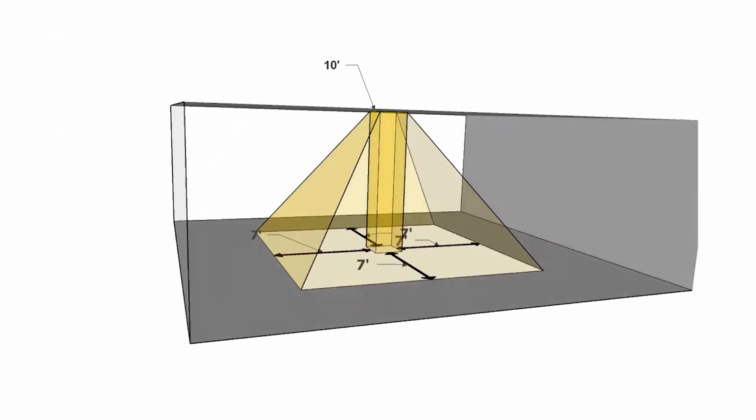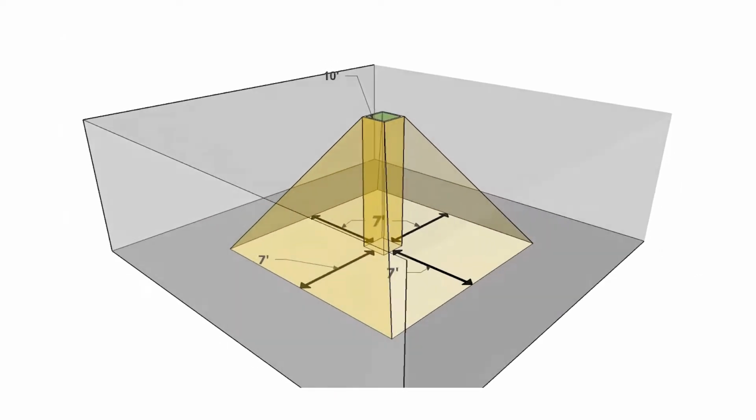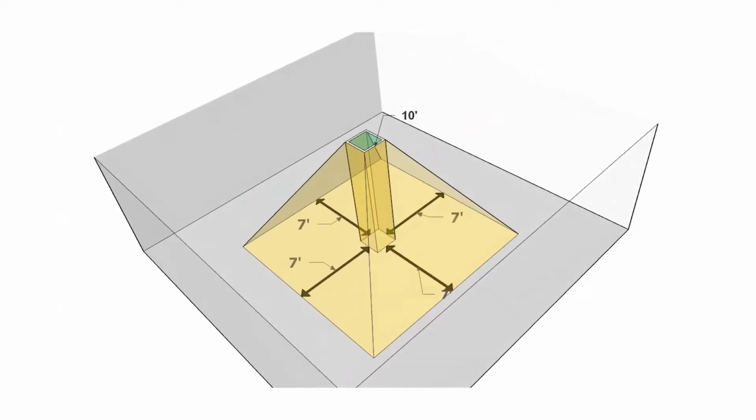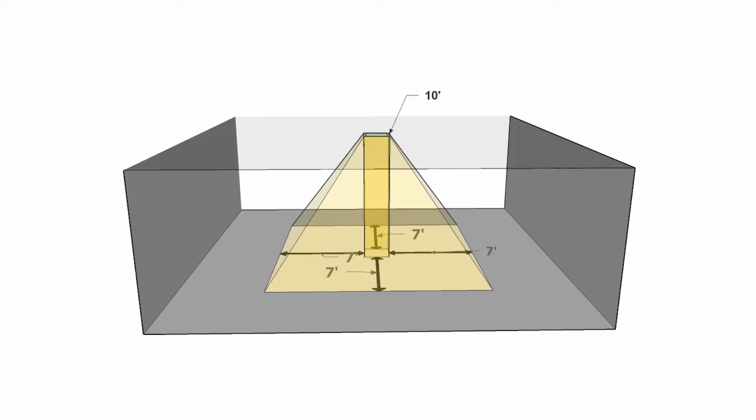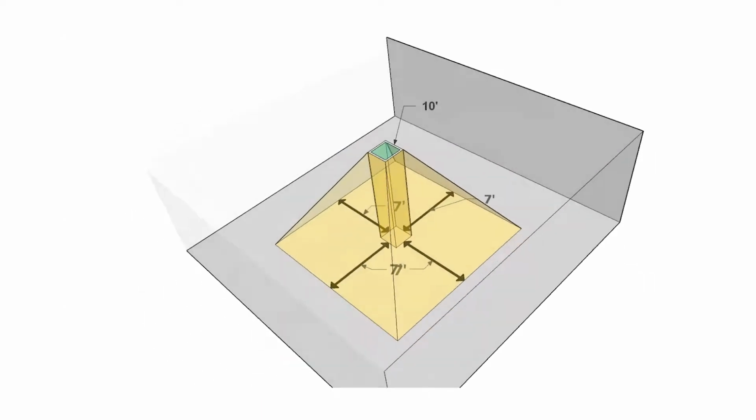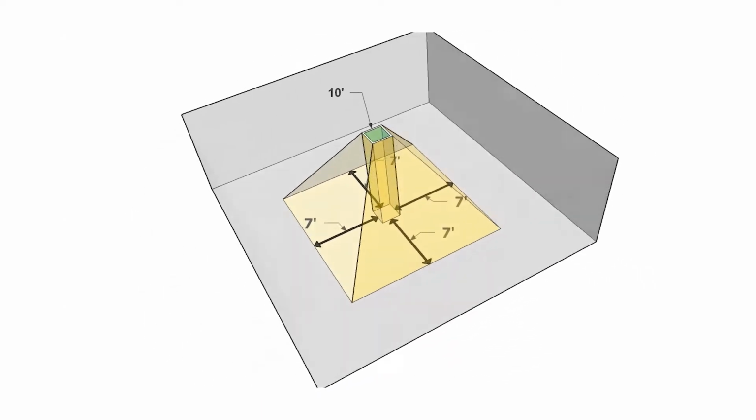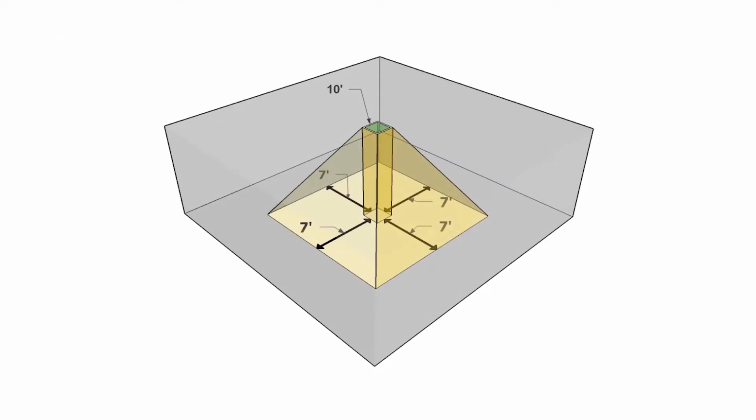It extends 0.7 times the average ceiling height in each direction from the edge of the rough opening of the skylight. It does not include any daylit areas that fall beyond a permanent obstruction that is taller than 1/2 the distance from the floor to the bottom of the skylight.